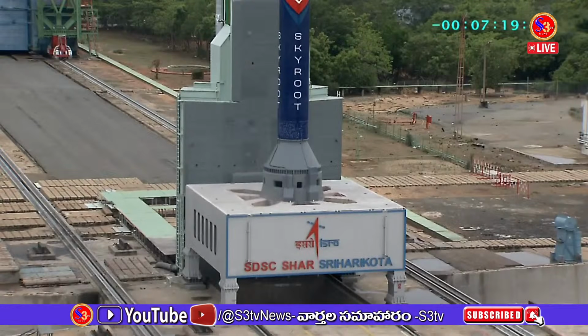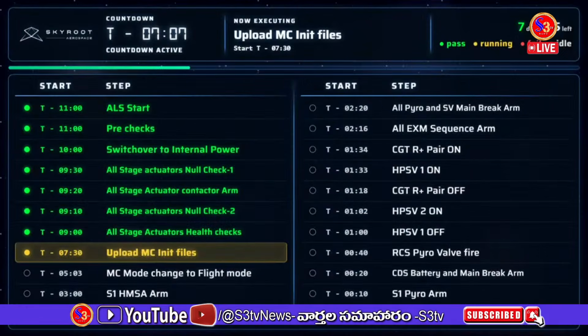So what engineers do is they perform something known as a null check. Essentially, they try to hold the nozzle in a neutral position. And then once that is confirmed, they provide small commands to the nozzle to deflect it. And if the response is deemed to be normal and the position is correct, we can rest assured that the rocket will obey every command that is issued to it by the guidance computer.